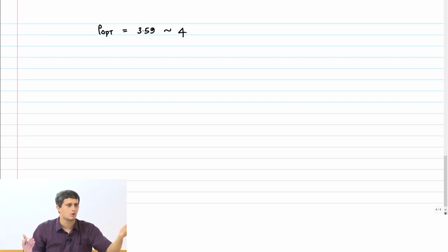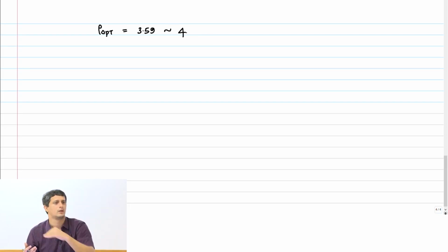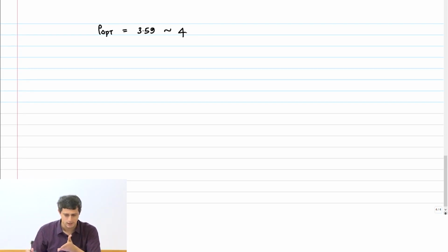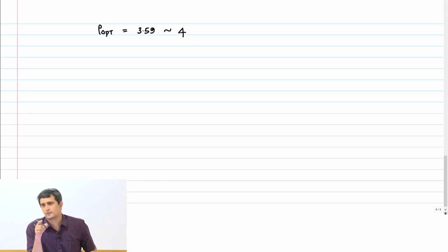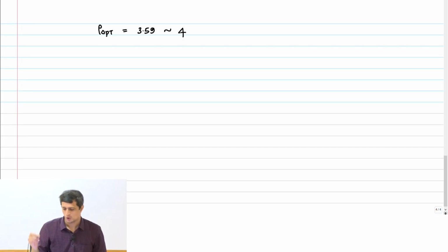I would simply go in sizes of 1x, 4x, 16x and so on. You get the reason is the theory that you do here. Inserting buffers and getting an optimal stage effort of approximately 4 is the best that you can get. You can't get better than that. Clear? So, of course, now we need to translate this into how many buffers or how many inverters we wanted to add.